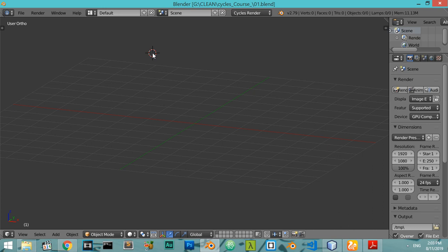In the Internal render engine, you can build a material by choosing diffuse and specular shaders from the material window, by setting several surface options, and then by assigning textures, both procedural and image maps as well. All of these steps make one complete material. After this, it's possible to combine two or more of these materials by a network of nodes, thereby obtaining a lot more flexibility in a shader's creation. However, the single materials themselves are the same as those set through the material window. Shaders made for a scanline rendering engine and their results.